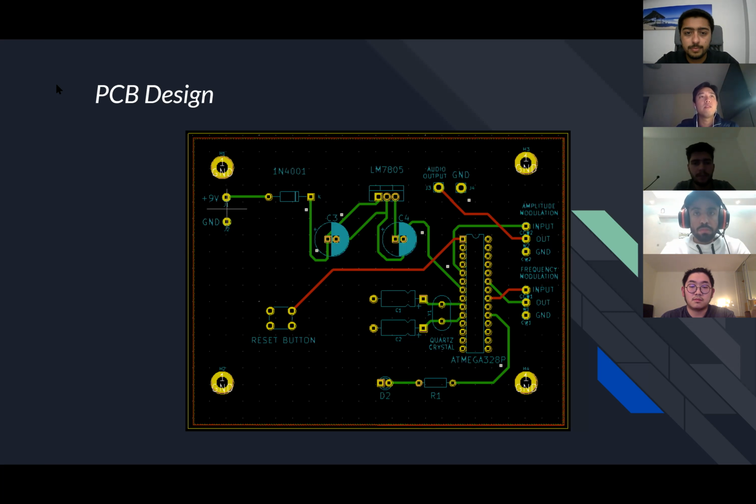This is our PCB design after adding the traces in order to check for any errors in the circuit design. We connected each component in the correct position and used the front and back layer of the PCB board to have enough spacing between each trace and to prevent overlaps between them, and also to prevent short circuits that may result in damaging the components or even the whole board.